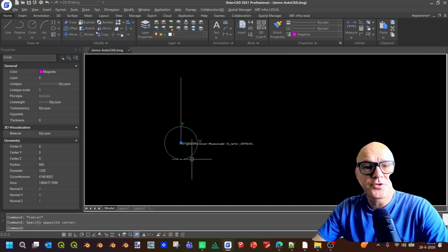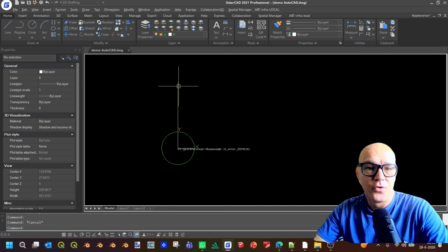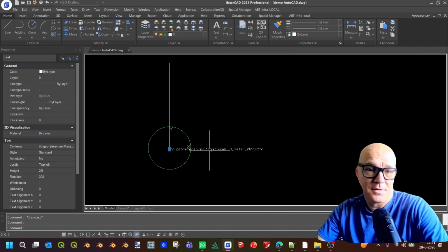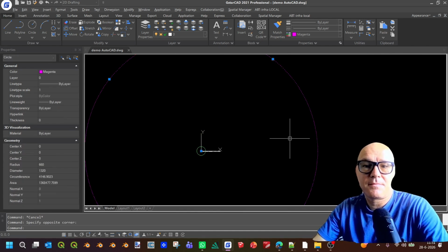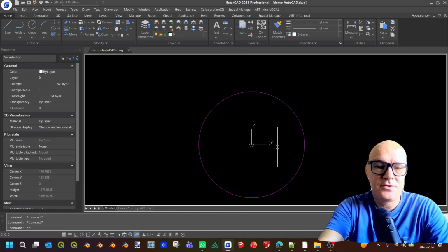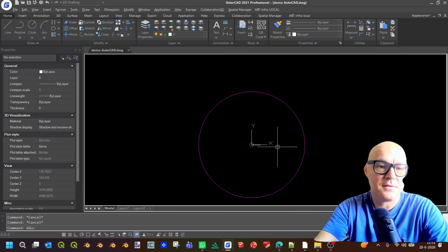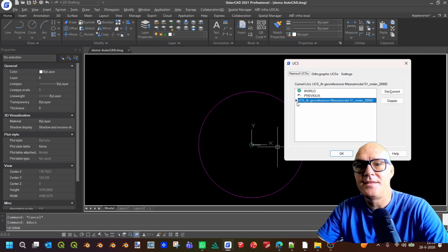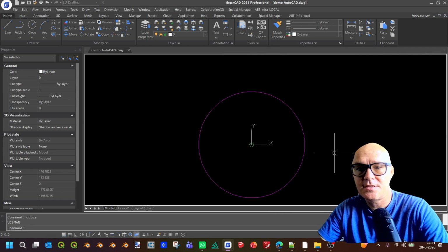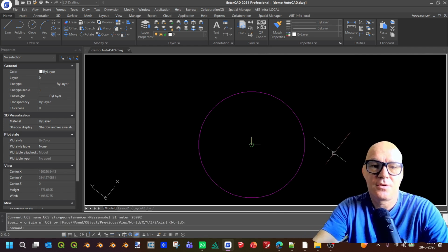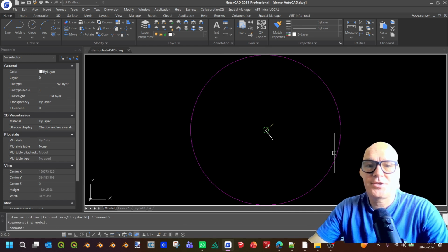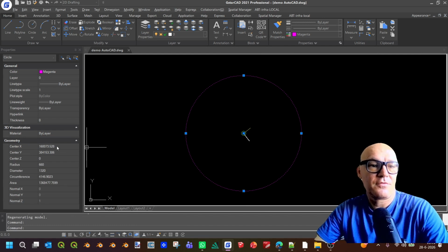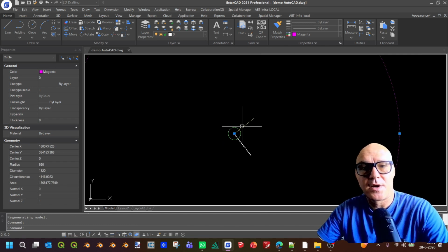As you can see, now it draws circles, it makes the north visible, and it displays the model name. But what it also does, it makes a UCS. It's an AutoCAD principle. It defines a UCS, and this one is now defined in this UCS. So if I do UCS world, actually on the grid map, this is the situation. You have these values, and this is my Z.